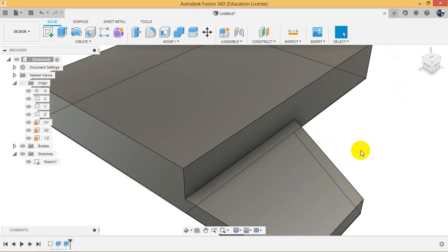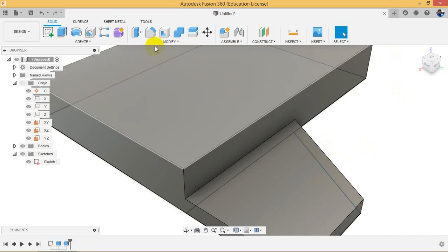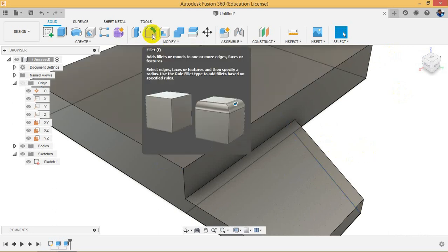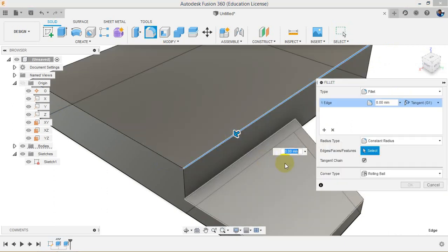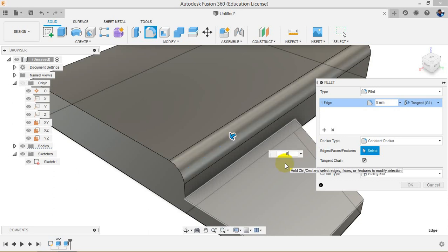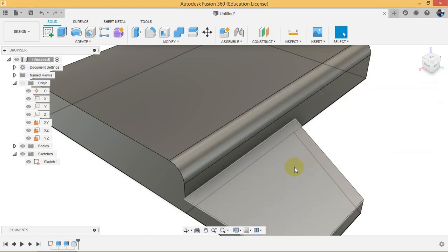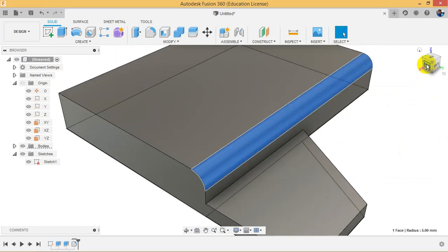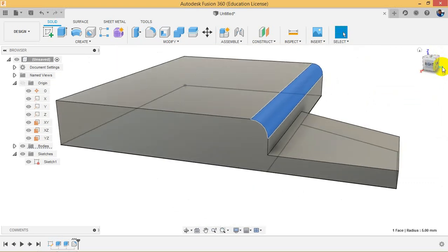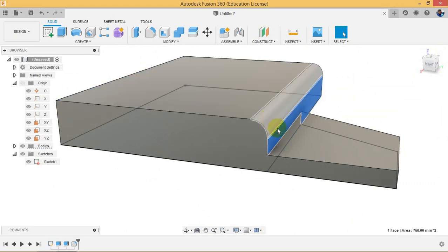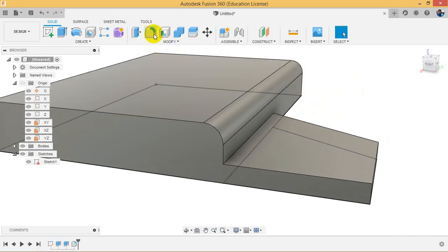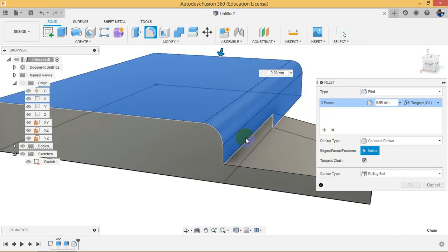As I discussed previously in the last class, the 2D fillet. This is the 3D fillet. What it does, you just select an edge and select the radius, like I pressed 5. So that creates the rounded shape in the edge. So this edge is not sharp, that's rounded, and this round edge, round face is tangent to this and this face.